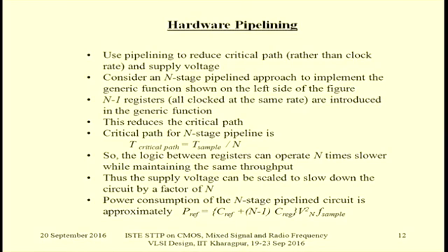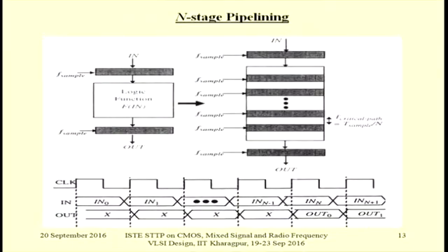Overhead means, in terms of the platform registers, that so many registers have to be used. We cannot ignore them. That means these registers have to be fed power. So although power can be brought down, it is not the rosy picture that we give, that is, not 1 by n times, because the overhead capacitance due to these registers has to be considered.